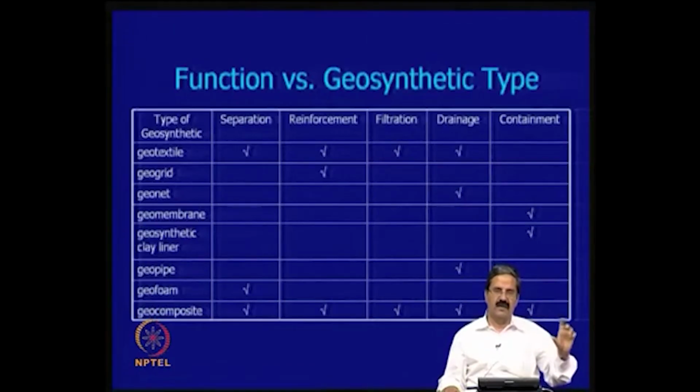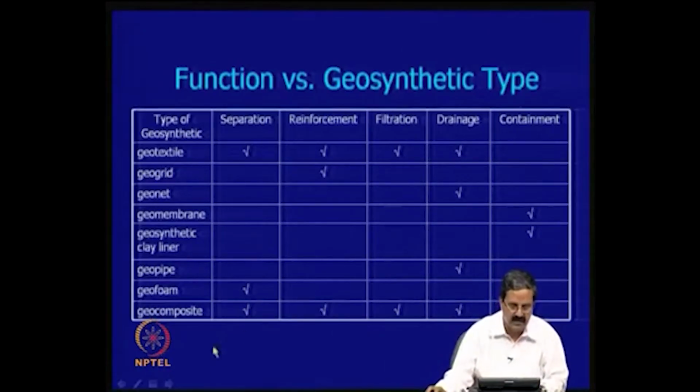So, what is the function in the pavement? Each member, like the bottommost member, has a low strength, the next one has a higher strength, the next one has still higher strength, like that. In no way should that be diluted, because load distribution is an important point in flexible pavement design. If the load distribution is not there, then the road totally gets damaged. So, if you put a separate layer, all the three layers behave separately and do their job properly. That is an important concept here, and this is where the separation comes in.